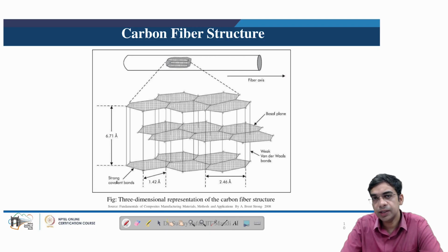As we have seen in the manufacturing process of carbon fiber, we start with an open linear chain like structure in PAN, and then we end up with a closed ring type of structure. We also conduct various processing of the PAN based fibers to remove other atomic species from the polymer chain, thereby leaving only the carbon-carbon bonds.